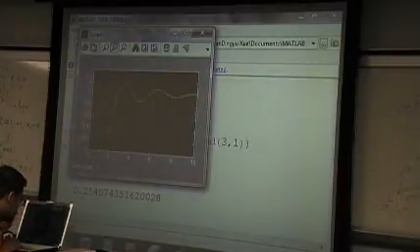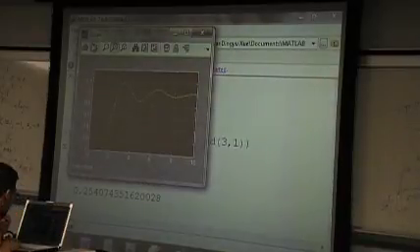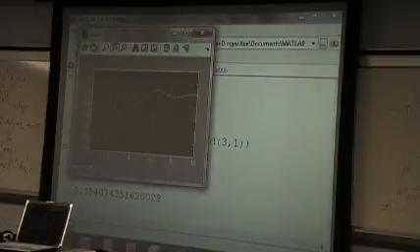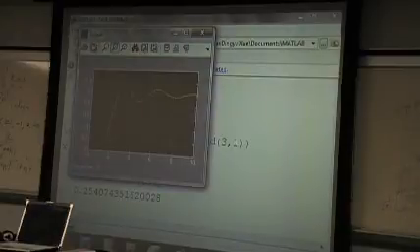However, the ITAE criterion doesn't have any frequency domain form, so we have to solve this kind of problem by computing. When computers were not very popular, old control papers usually used the ISE criterion.